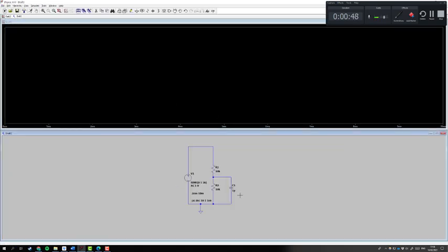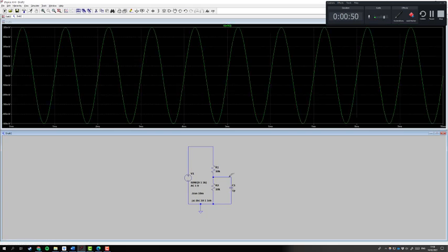And again, as before, we need to click on a value, and at that 10 picoseconds, it's going up and down. It's supposed to be one volt, but we only get half of that because it's 10k and 10k, and it's a potential divider with half the value coming out. So everything is as before. That capacitance isn't doing anything.